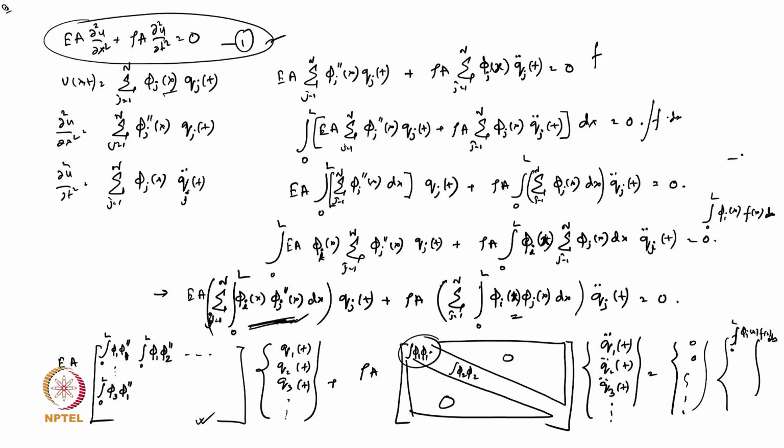But in the spectral element case you will not reach that stage. There you have to take the excitation and go for the Fourier transform, so that you get the frequencies contained in the Fourier domain or frequency range. You have to calculate the responses for each frequency, multiply both of them and you will get the solution.